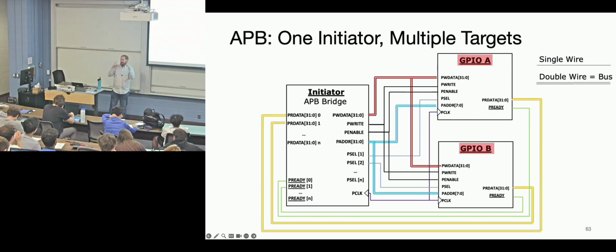And if you're a medical device, you put 3 D flip-flops, because statistically, it's unlikely that the in-between edge will propagate through your circuits through 3 D flip-flops. If you add 3 or 2, that still adds a delay, right, or no? Yes, it's going to add a 1 cycle delay to each one. And then you might come back and argue with me on an exam and say it was only 3 clock cycles out, and you're trying to figure out when the human pressed the button. Does it really matter? So you have to figure out, is 3 cycles of latency important?